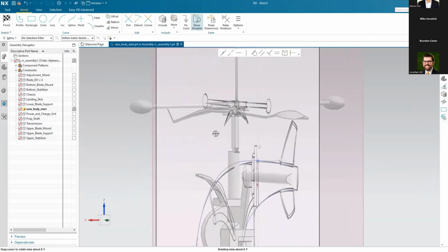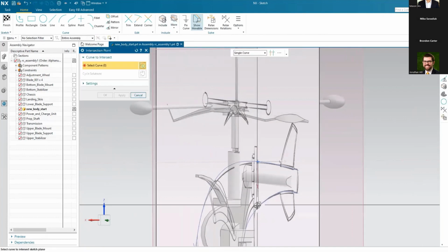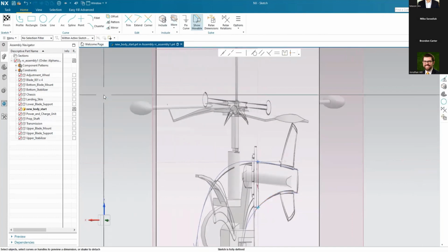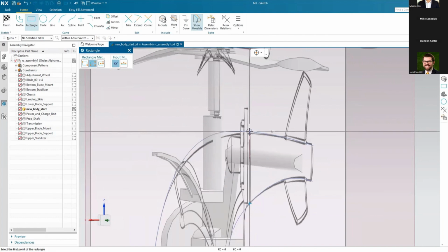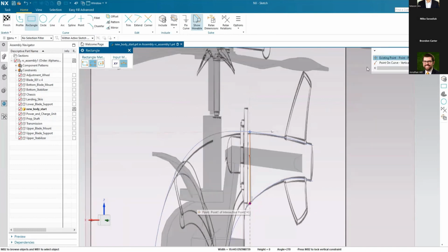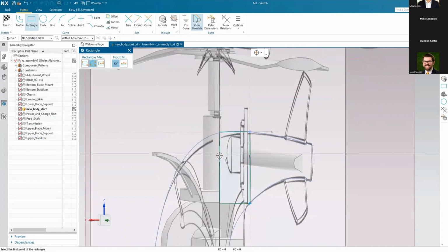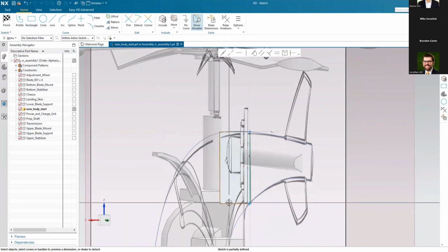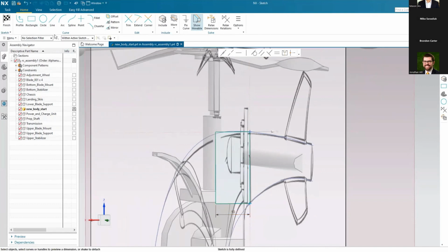You saw me do some freehand work, but here I want to have some geometry that I can control with parameters to do some different sizing for this particular tail end of the RC helicopter. What's nice with these is it's not just putting it out there, it's intersecting with some of the other geometry, so that if we make changes, the geometry and the shape that we have here will maintain and be connected to that so that we don't break that downstream.